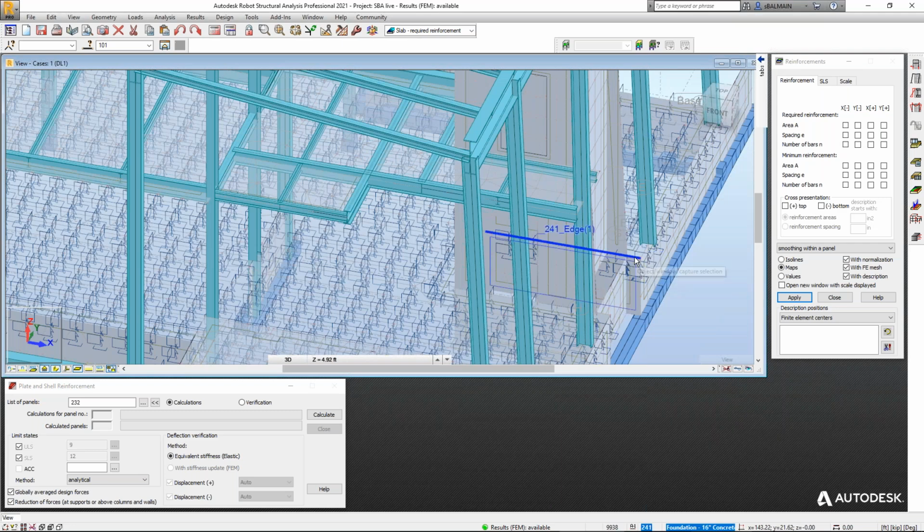And so if you start in Robot and after you update and you create the Revit file starting from Robot, it's possible, but you need to adjust the 3D. Of course, the analytical file will be perfect because it comes from Robot, but you will need to adjust a lot.